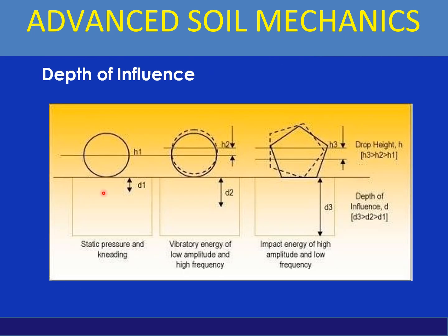So you can see the depth of influence in the case of static pressure and kneading, and this is vibratory energy of low amplitude and high frequency. You can see that the depth of influence is more in that case. And look at the impact energy of high amplitude and low frequency. So you have the maximum depth of influence in this.